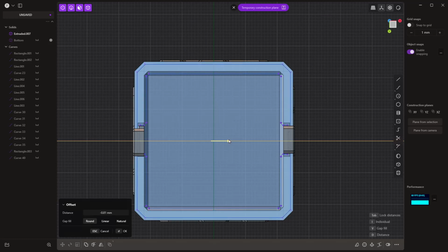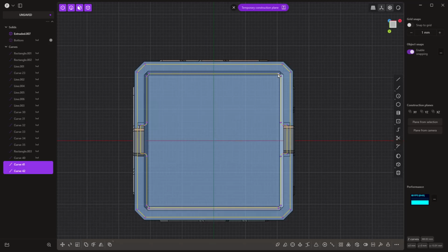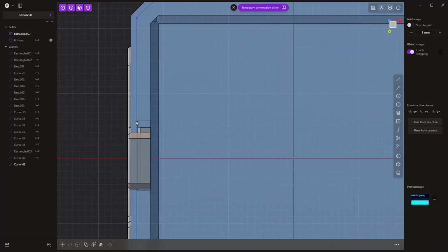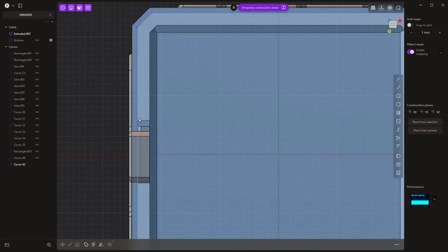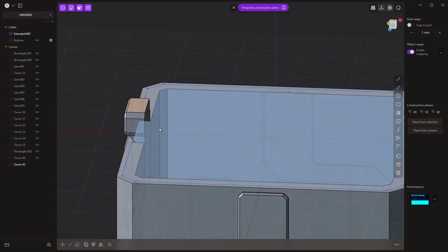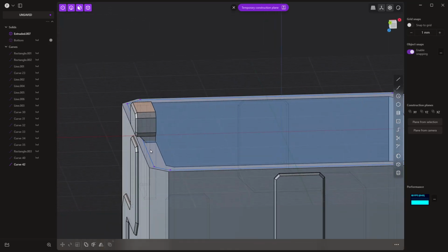And what I'm going to do is just offset that. Let's see, right about there, it's minus 0.88. The inside one isn't needed, so I'm going to delete that. And I don't want this lip to be everywhere. We could put it on just the sides, but putting it underneath this is going to be problematic because remember, we do have that sort of big chamfer there.